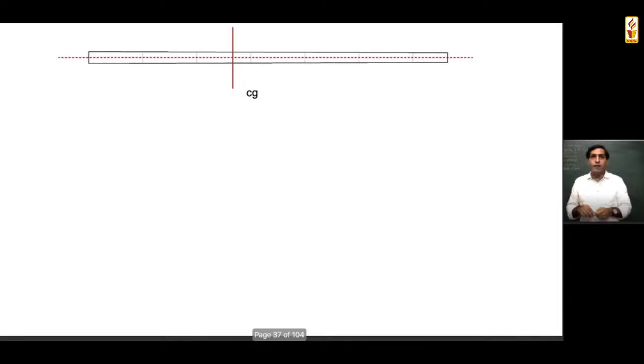The next important thing: if I am trying to find out the center of gravity of steel and the center of gravity of timber for a uniform section, in case of steel, you will find absolutely the geometrical center. In case of timber, you will find a variation of not more than 1 centimeter most of the time, because there is non-uniform density in timber, unlike steel. But the moment you go into bamboo, the density variation becomes much more, which means that your center of gravity will not be your geometrical center. In most cases, this variation could go as high as around 30 centimeters, which means that when you are constructing a structure, you think you are treating it like steel where its CG will be perfect. That would not be perfect, which means in reality there will always be an eccentric load working on the structure.